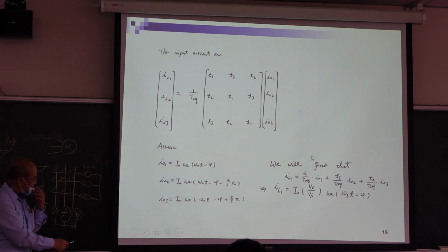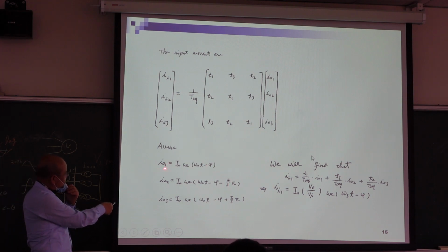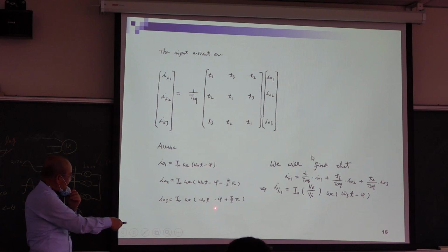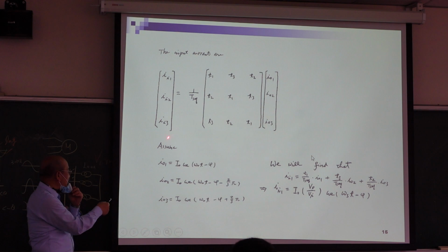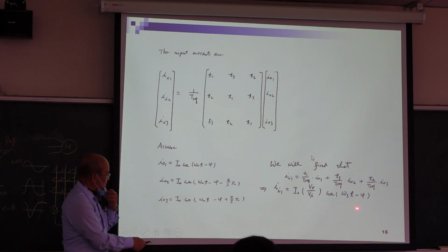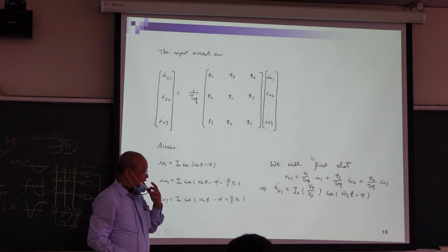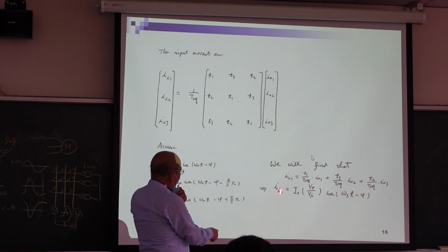So the output is lagging. You can see the output voltage is 0, but the current is on the minus side, which means the output current lags the output voltage. So it is lagging. If the output is lagging, how about the input?